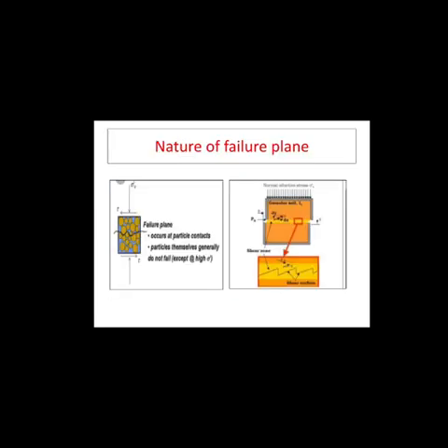It should be noted here that the failure plane is a weak plane along which the soil mass gets sheared. The shear plane never cuts the particles of soil as they are hard soil particles. Microscopically, the shear plane follows a zigzag path, avoiding the hard soil particles and taking the path of least resistance. However, these planes follow the general shear failure patterns. With this brief introduction, let us proceed to study the shear strength of soils in detail.